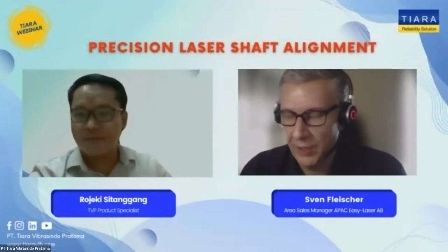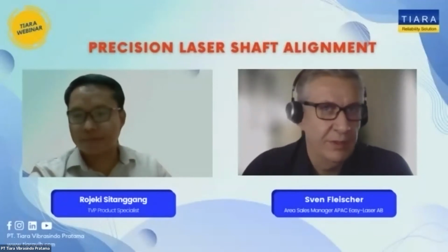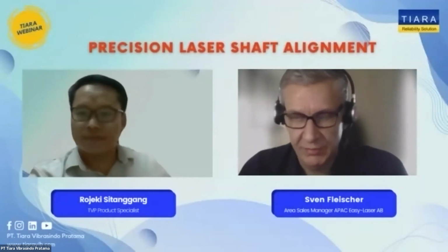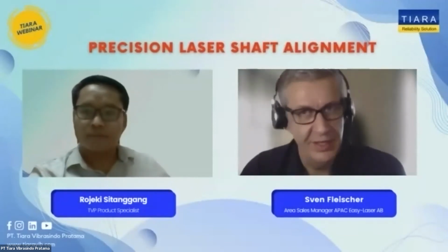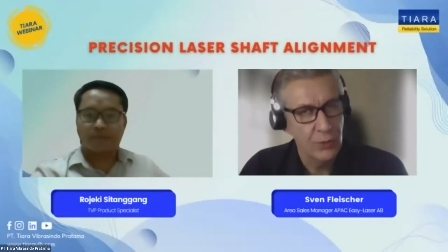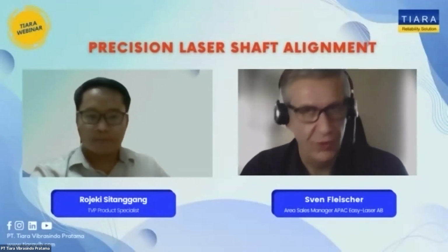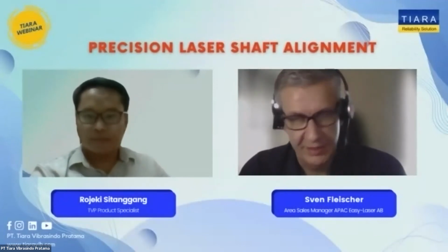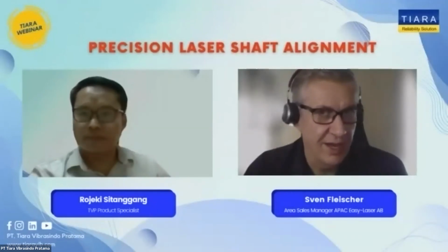Yeah, okay. So we have in measurement technology together with brackets that are installed on the machine coupling flange. This requires taking off the joint or the cardan itself. So that's called in-situ cardan alignment.